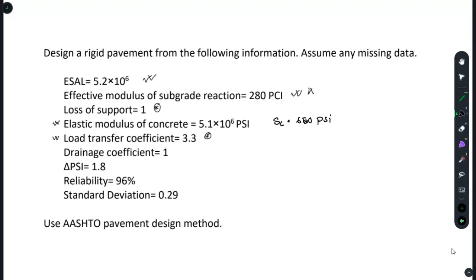If it is 1 or 1.2, it indicates that it's a good road drainage system. And if it is less than 1, it says that the drainage condition isn't good. It is actually based on inspections, considering specifications. Then you just name it 1 or 1.2 or 0.4. There is no direct measurement, it's just inspection. We use those inspections, assign numbers to them, and then use them for quantification.